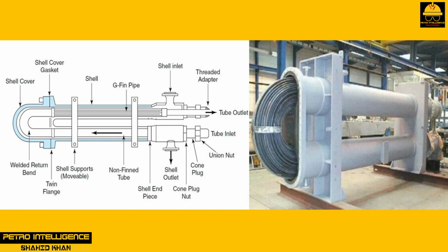The double pipe design consists of a pipe within a pipe. Fins can be added to the internal tube's external wall to increase heat transfer. The multi-pipe hairpin resembles a typical shell and tube heat exchanger, stretched and bent into a hairpin. The hairpin design has several advantages and disadvantages.